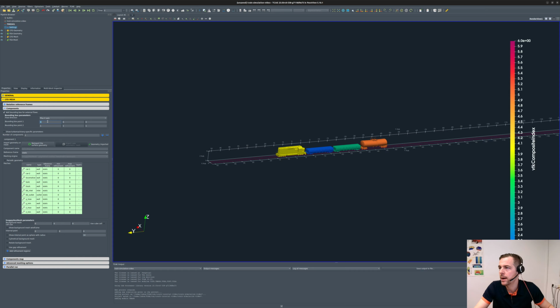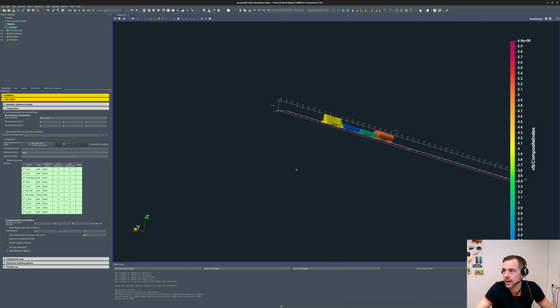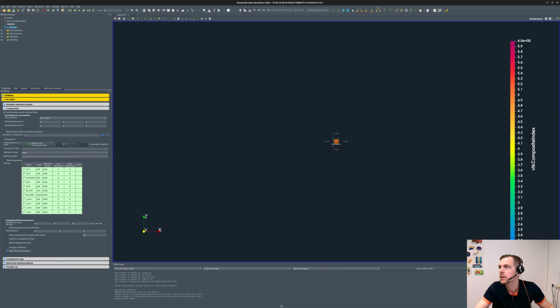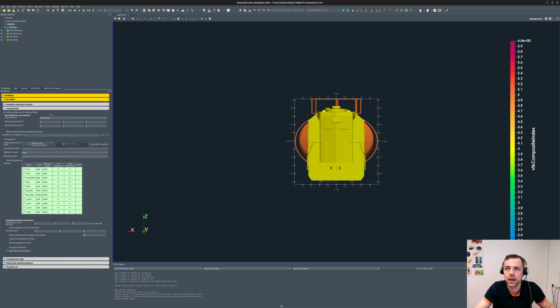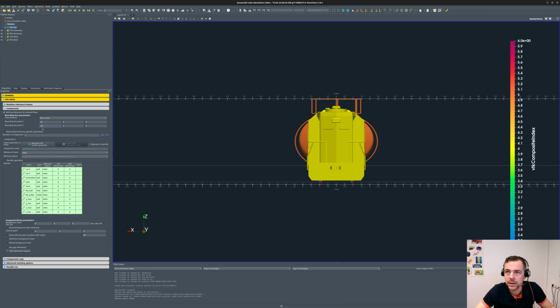So my train starts somewhere in X direction. Let me see. Yeah, in X direction, it's like 5 meters wide. So I'm fine with that. Okay, let's do it. Let's do it 20 meters on the left side and 20 meters on the right side, and minus 50 meters, because my flow direction is in y direction and minus y, so that's the property which I did.